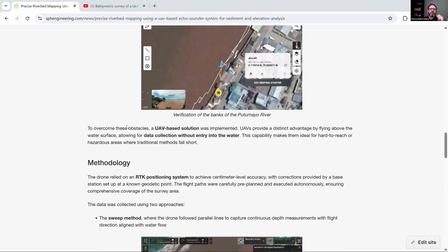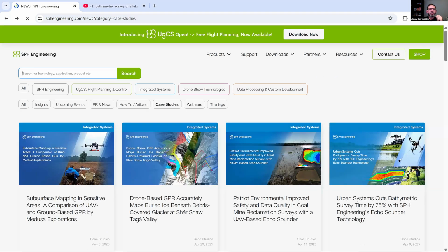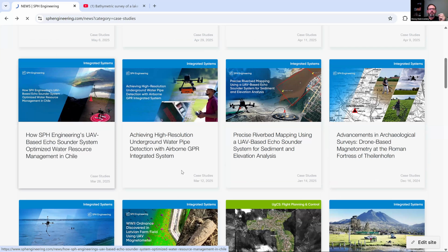I would recommend using a simple single frequency echo sounder for the repeatable surveys. Standard basic system. If you expect that the bottom has a lot of vegetation, I would recommend a dual frequency echo sounder, model called D24, to have clean data from the bottom, not from the vegetation. You can find, I think, a few case studies exactly for that scenario on our site. If you are interested, we have a lot of data. This one is very similar, actually.